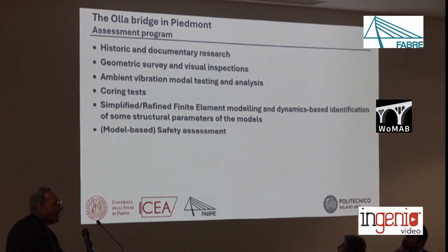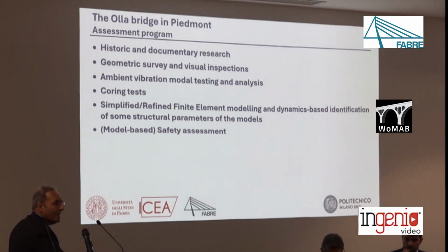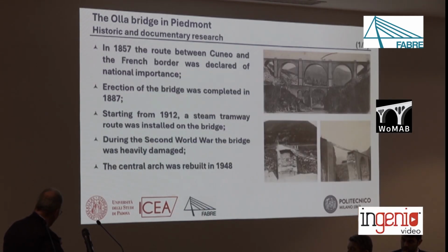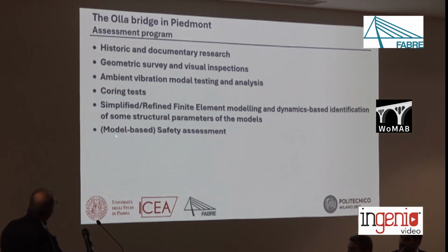At the beginning of our investigation, no documents were available on this bridge, and so the research that we performed involved historic and documentary research, geometric survey and visual inspection, of course ambient vibration modal testing and analysis, some few coring tests, and afterward all this information was collected in two numerical models, one simplified and one refined, and the model-based safety assessment was performed after the calibration of the model.